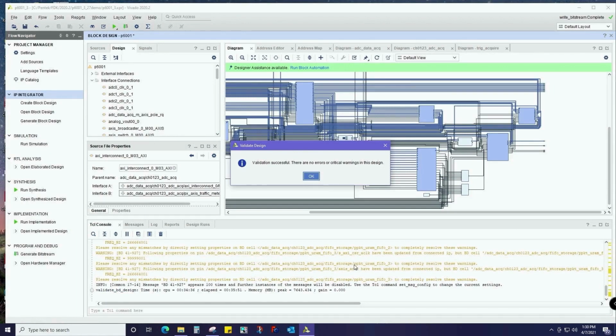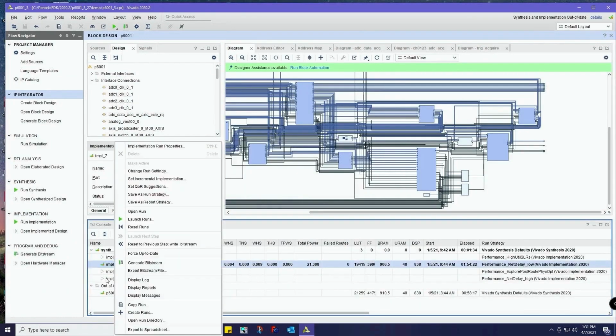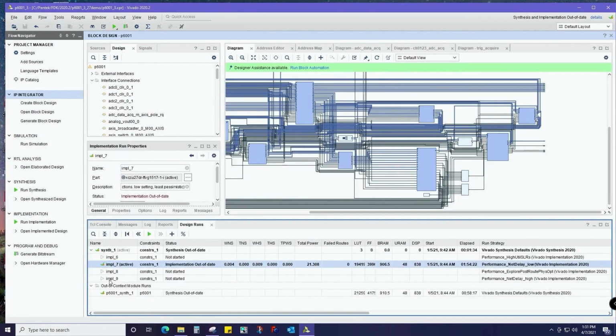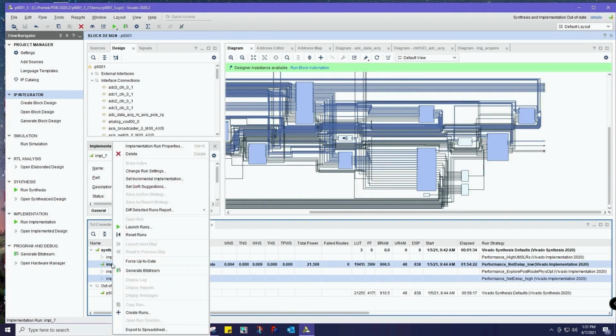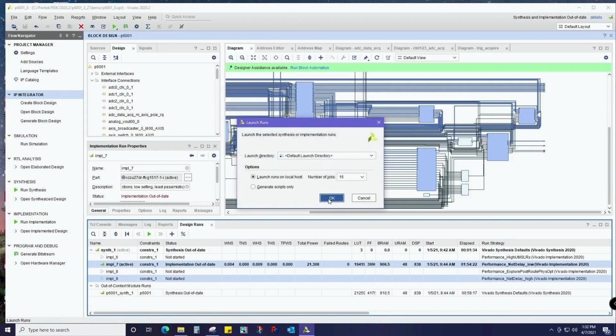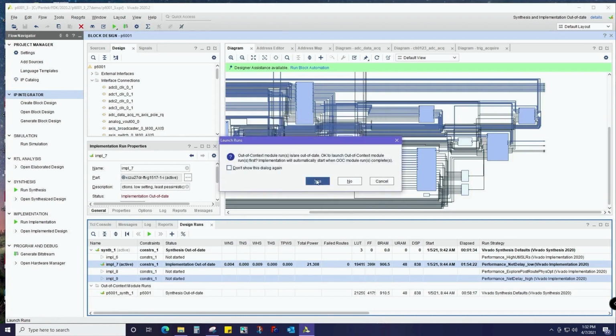Once the design is validated, we need to synthesize, implement, and then generate the bit stream. And I'm going to jump through this pretty quick because all of these are pretty mechanical steps that Vivado will do for you. I will pause here for 1 second though and show you that I'm choosing 2 different strategies. These typically from experience tend to produce a good route, so between the 2 of them I expect at least 1 good timing score. And with that we launch the synthesis in place and route, and that will take a while, so we'll speed that up and come back.